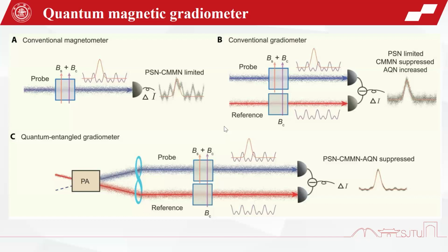So it does not contribute to signal, but it also contributes to noise. Although it's a differential measurement, these two channels have independent Gaussian white noise. So it still increases the quantum fluctuation. And if we want to have more, for example, in MEG, there are hundreds of sensors cooperating together, and this will increase a lot of noise.